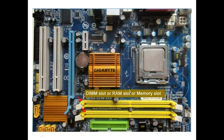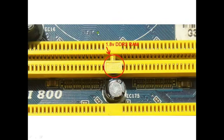These yellow color slots that we see here are called DIMM slots or RAM slots or memory slots. They hold the primary memory, that is RAM. DIMM stands for dual inline memory module. At the center of this DIMM slot, on the notch, there is a voltage written. It is 1.8 volts here.